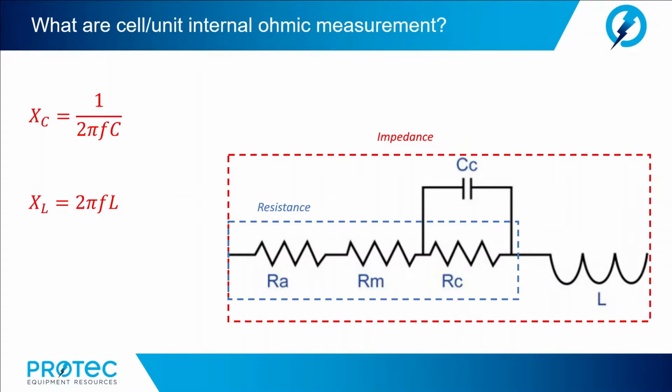However, IEEE has recognized the great value for choosing one device for ohmic measurement, no matter who makes it or the method to calculate the ohmic measurement. The only caution given by IEEE and the battery manufacturers is that when trending the cells of a battery, consistent ohmic measurement devices should be used to establish the baseline measurement and to trend the battery set for its entire life.